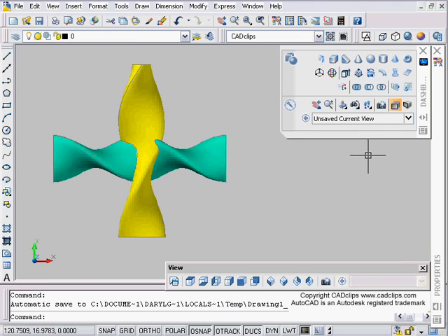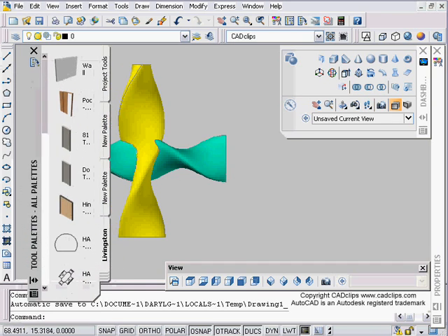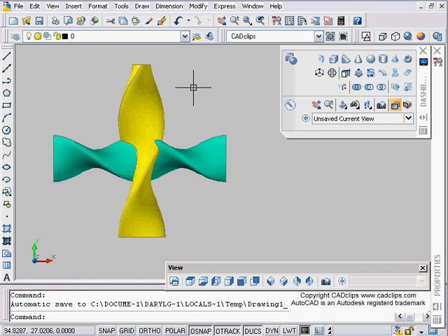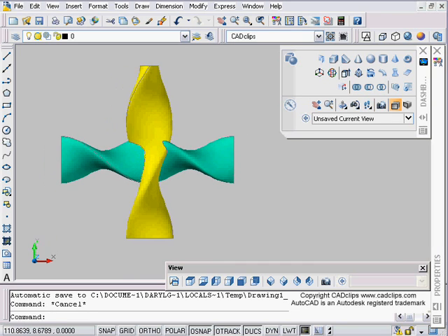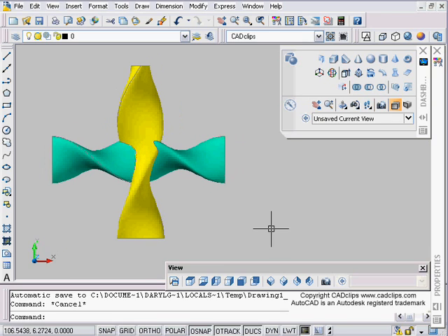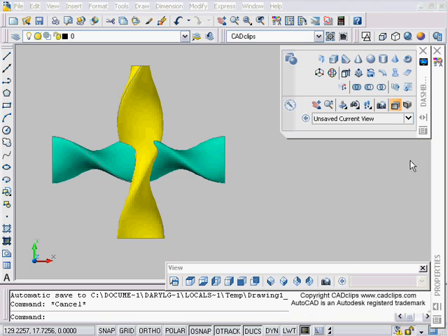Hello and welcome to another CAD clip, AutoCAD 2007 3D. In this lesson we're going to talk about the new sweep command. The sweep command is nothing new; the difference is that the interface is a little different, and you don't have to align the profile you're sweeping with the path. That part has improved, which makes things so much easier when teaching 3D, because you're using your UCS a lot less now, and it's become a lot easier and more intuitive.